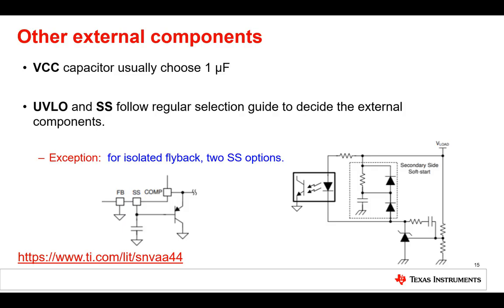The undervoltage lockout UVLO of a converter makes sure that it turns off when the input voltage is too low and does not turn on at low input voltages. So the design of the UVLO components is important to make sure that the converter only operates when it is safe. See the datasheet or user's guide for these components.